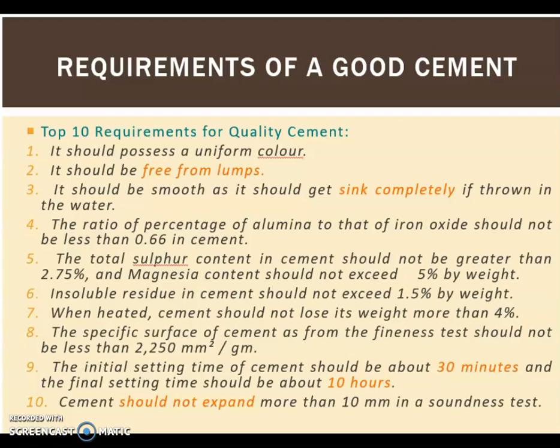Okay, see what happens, certain ingredients, when they are more, can make the cement unsound. So when you have sulfur, it is obviously useful in making good sound cement, but in very small percentages. If it is in excess, the same cement can become unsound. What do you mean by unsound? It can expand, it can disintegrate when it is in the form of mortar or in the form of concrete. If there is too much of certain compounds like sulfur, then the concrete or mortar can disintegrate.